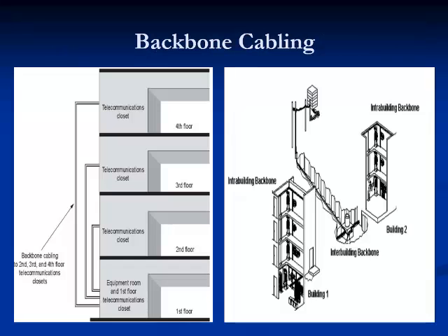The third subsystem of structured cabling is called backbone cabling. Backbone cabling is sometimes called vertical cabling, cross-connect cabling, riser cabling, inter-room cabling, or intercloset cabling. Backbone cabling is necessary to connect or tie the entrance facilities, equipment rooms, and telecommunication rooms together. Backbone cabling includes cabling between equipment rooms and building entrance facilities, in a campus environment, cabling between buildings, entrance facilities, and vertical connections between floors.